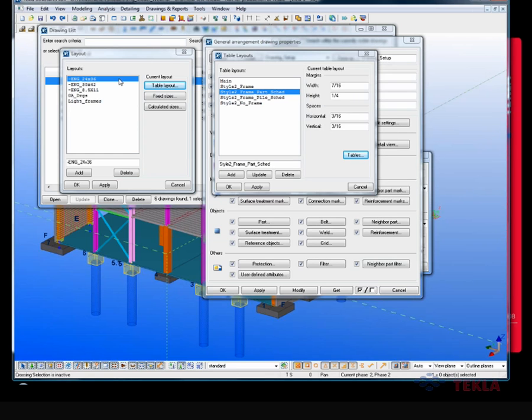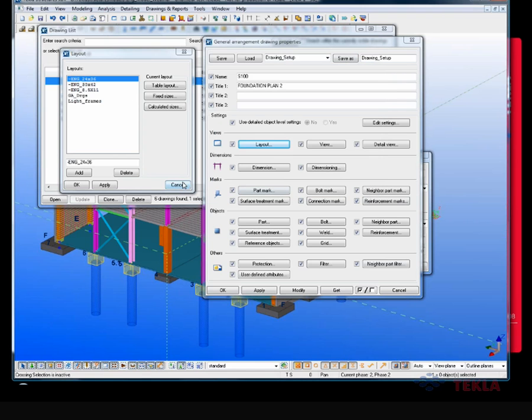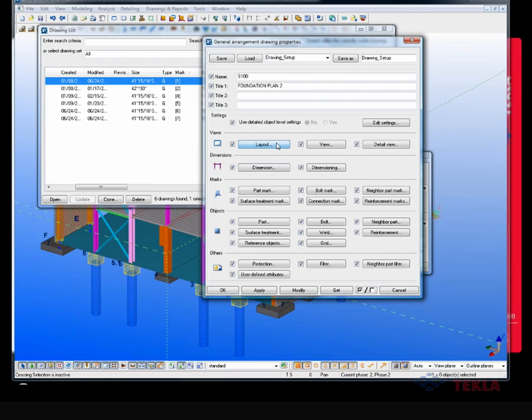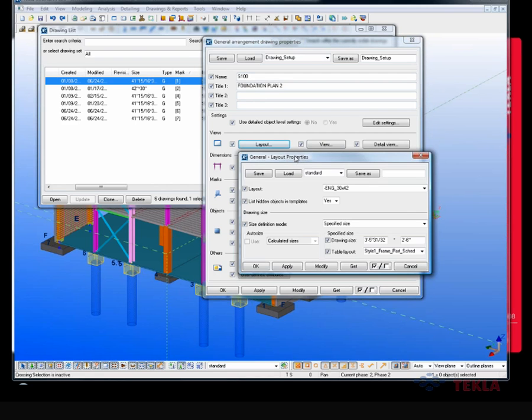So note here that there's layouts here, and these layouts are saved as a .lay file. So you would see that in your environment folders, or as you created your own, they would be a .lay. And then corresponding table layouts for each for a given layout. Now that information is pulled in again once you get into the sheet layout.